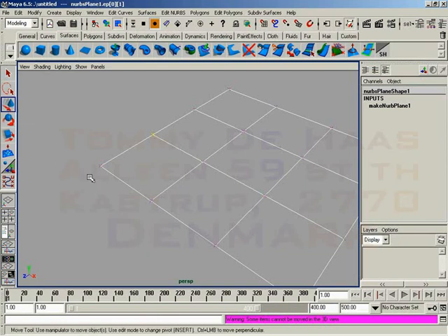That's right. You cannot manipulate the location of an edit point directly. You need to go in and move the CVs. That's just how it works with NURBS surfaces. With NURBS curves, you can go in there, grab edit points, move them around all day long. You cannot do that when working with the NURBS surface.